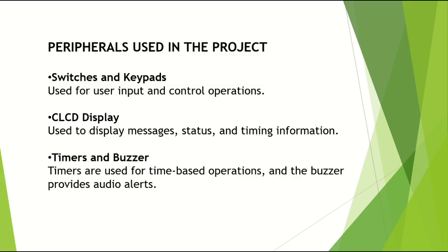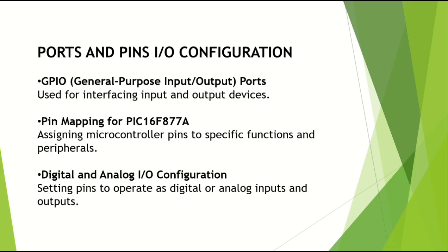Ports and pin input-output configuration. GPIO means general purpose input-output ports, used for interfacing input and output devices. Pin mapping for PIC16F877A is the assignment of controller pins to specific functions and peripherals. Data and input-output configuration sets the pins to operate as digital or analog inputs and outputs.